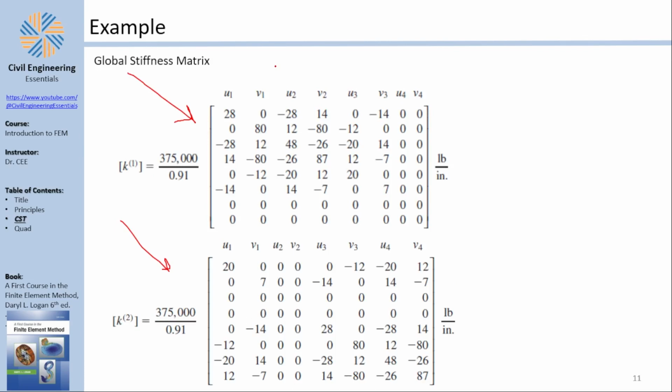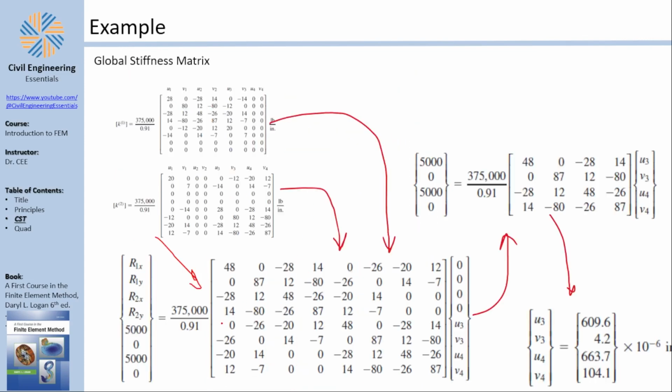We don't need the transformation matrix, or the transformation matrix, for the mathematics nerds, is an identity matrix. So we expand our stiffness matrix by adding zeros. That's not important, because you could just add them together like we did selectively. You add them together and you get your global stiffness matrix. There is nothing else I want to say for now. You have stiffness 1, you have stiffness 2, you add them together to get the global stiffness matrix.